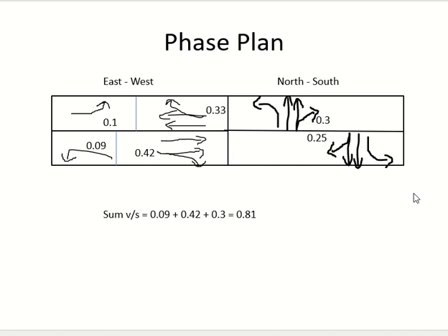I'm not doing it for traffic. It will not pass with the traffic. You are just giving extra time. The time according to traffic is already enough. According to the book, they are saying we add it to the through mode. So whatever 8 or 7 seconds extra we have, we'll add it here.